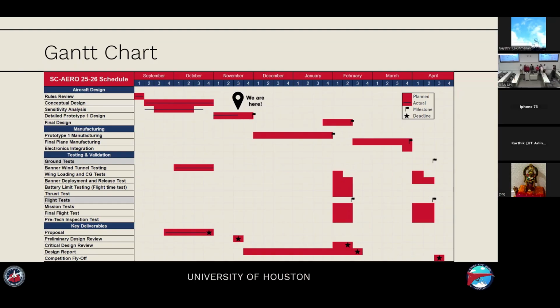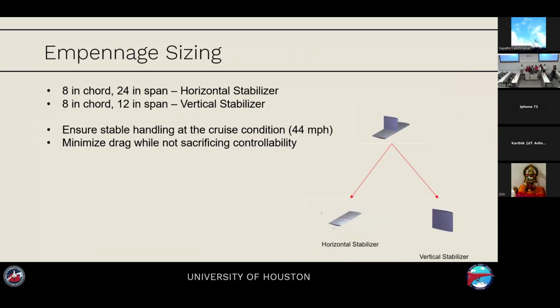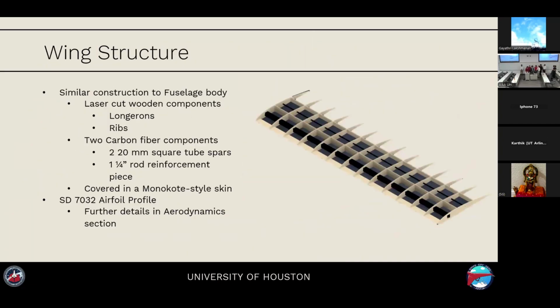That's the purpose of the 1/4 inch carbon fiber. It's an anti-torque bar. Okay. There's a second bar behind the main bar. You still get torsion because they bend a bit. As in, is that just having a really thick main spar, or is there a second? No, there's the main spar, and behind that, about an inch from the trailing edge, about half the trailing edge.